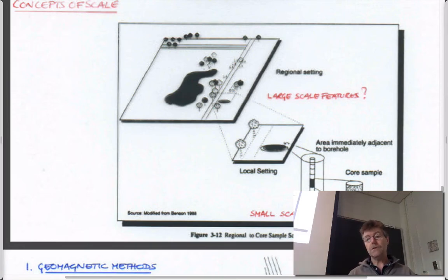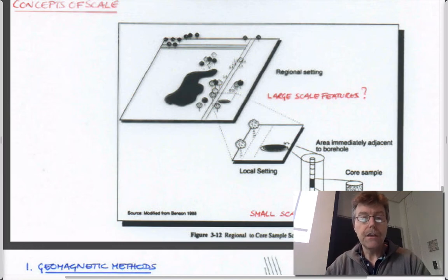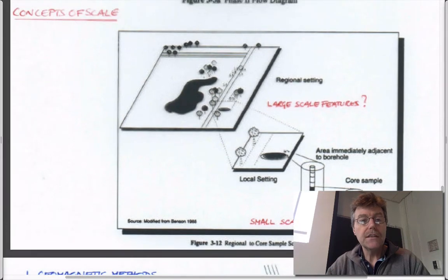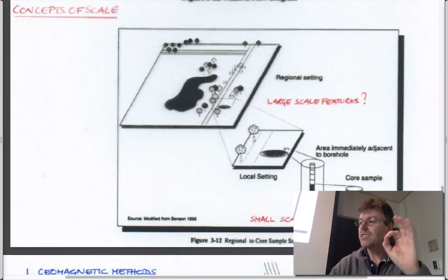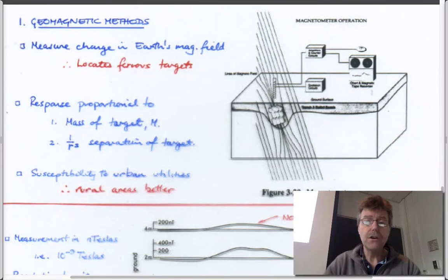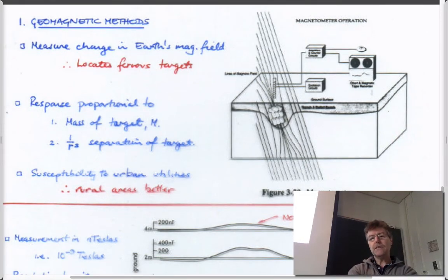And so what you'd use geophysics for would be that between two boreholes, you could run a geophysical survey line to fill in what the stratigraphy looked like between them. You know exactly what it is where it hits the boreholes, and it infers what the fill-in characteristics are over the rest of your site. And so that's really what we're attempting to do. And so the idea is that geophysics is less precise in terms of defining exactly what is there, but it allows you to join the dots, I suppose. And so we'll emphasize the ones that are used in environmental remediation or environmental geophysical surveys and to understand remediation.